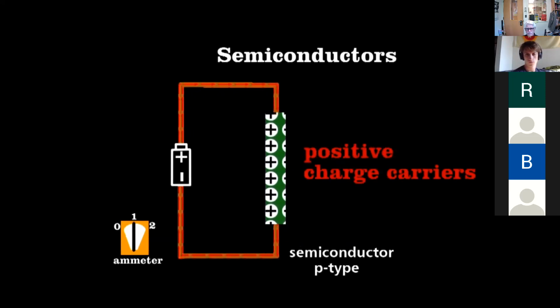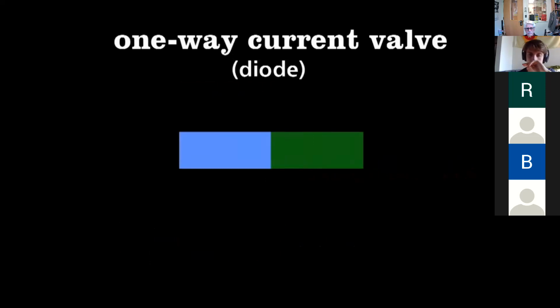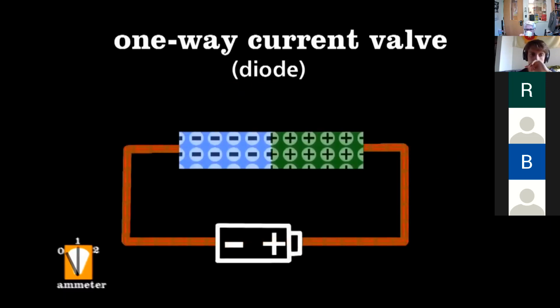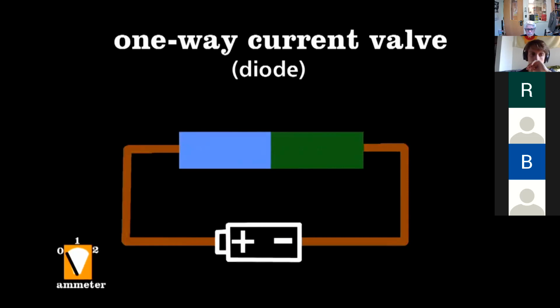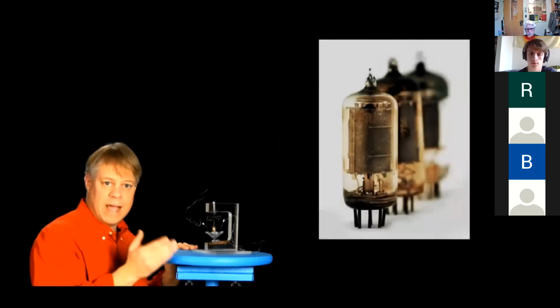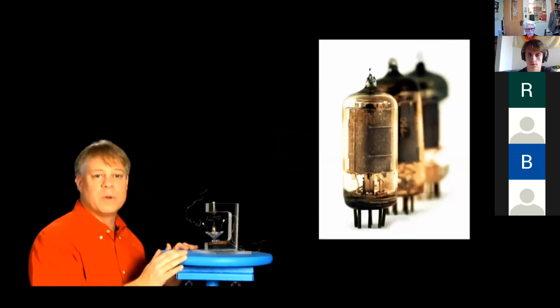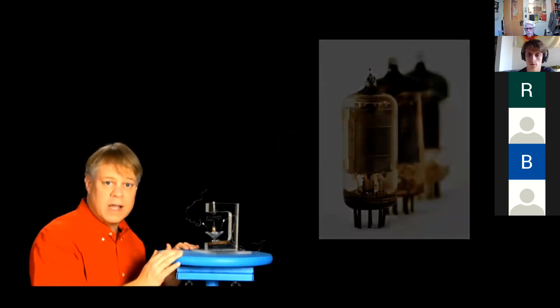It allows an engineer to make a highly reliable device that allows current to flow in only one direction. We can do this by making a sandwich with two types of semiconductors. Here, the negative charge carrier one on the left and the positive one on the right. This semiconductor sandwich allows electricity to flow; reverse the battery, and the current drops to zero. Other devices can do this, for example vacuum tubes, but they have many parts, were unreliable, overheated, expensive to produce, and likely impossible to miniaturize.